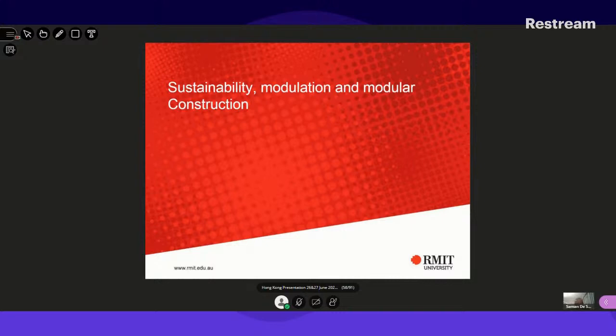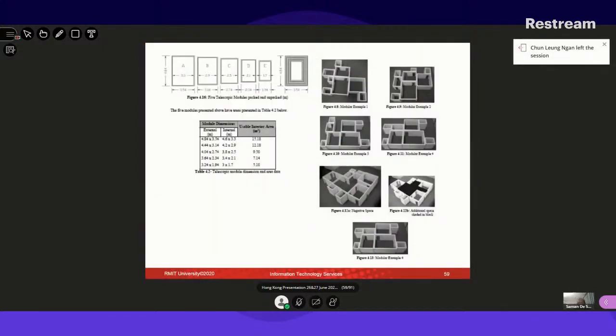Concrete finishes vary from S1 to S6, with different tolerance types, and the worst tolerance could easily be about 10 millimeters. They wouldn't mind that, for example, in below ground work most of the time. But you can't make that assumption in a building. So you have to find a nice detailing which goes with it. Those existing structural load bearing walls are not necessarily perfectly smooth.